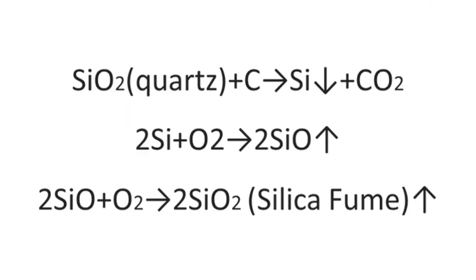Specifically, the formation of silica fume occurs when high purity quartz in a high temperature state is reduced. Approximately 10% to 15% of the silicon in this process is vaporized and escapes into the flue gas. The silicon vapor reacts with oxygen to form silicon monoxide, SiO, and this SiO gas meets cold air and combines with oxygen to form silicon dioxide, which then condenses into small spherical non-crystalline microbeads.